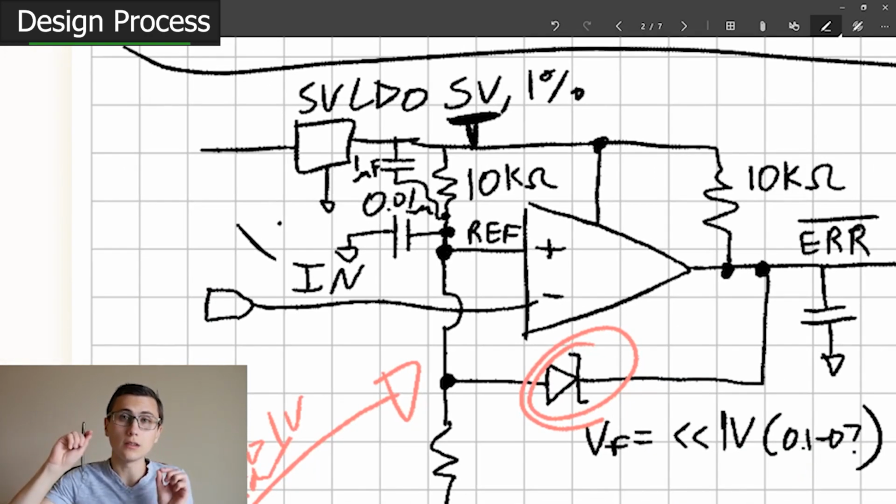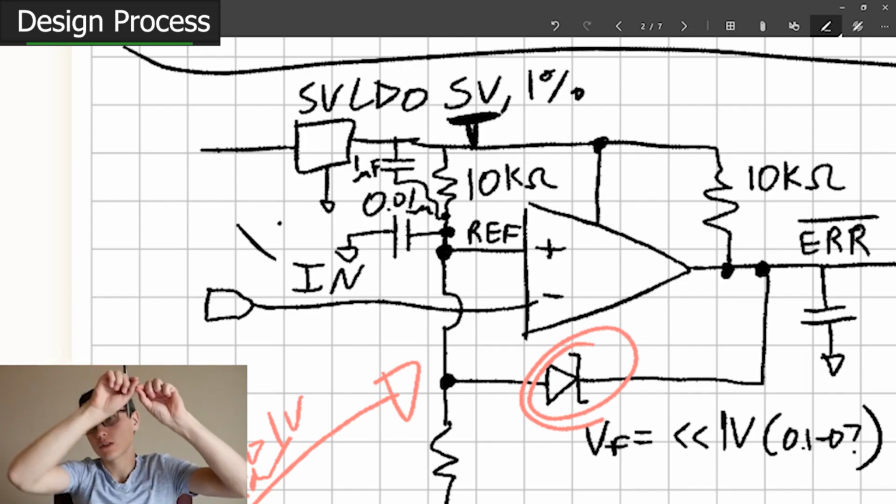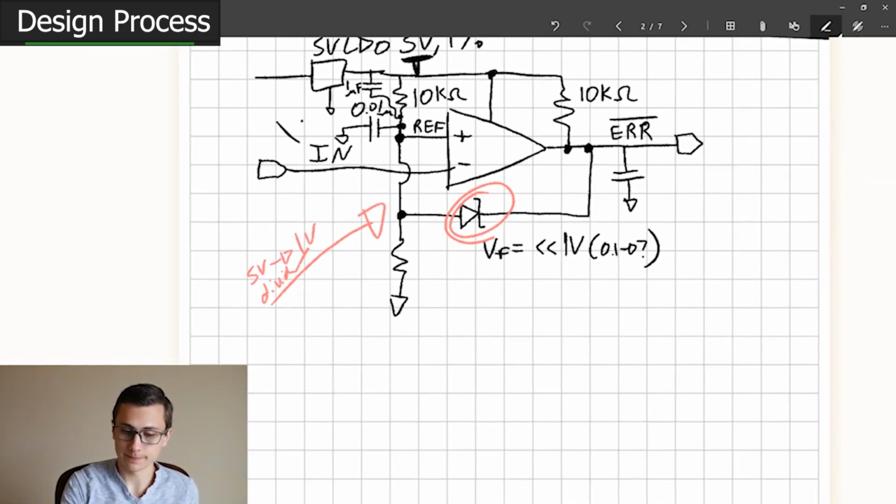That'll just give us a little boost of current, and we need to get into AC circuits so you might understand why, but basically that capacitor will ride up with the 5 volt rail. It'll go kapoing, and it'll drag that reference node up to about 5 volts, because there's 0 volts across the cap. If you pick up one side, it'll try to pick up the other. Then that capacitor will slowly discharge back through the 10K over time, but in that turn-on moment, when the input is 0 volts, it'll just make sure that we ride through that transient.